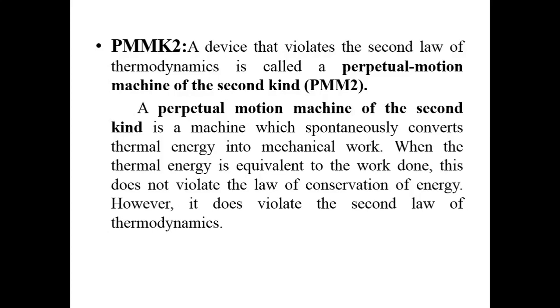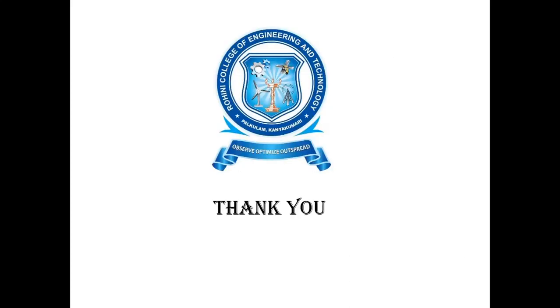So here it is spontaneously converting all the thermal energy into mechanical energy. When the thermal energy is equivalent to the work done, that means it is converting all the thermal energy available into useful work. But what the second law of thermodynamics says is that it is not possible to construct an engine which converts all the heat energy into work. Surely it violates the second law of thermodynamics, the PMM2 machine which spontaneously converts the thermal energy into mechanical work.